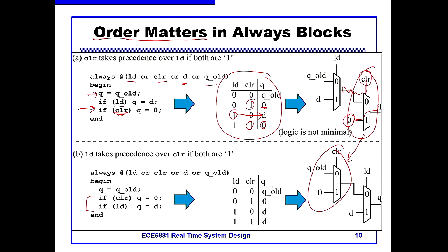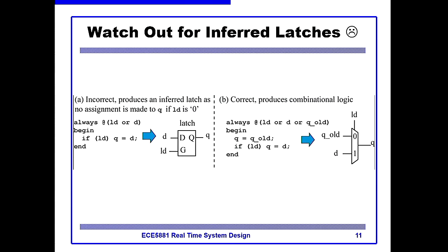Alright, so a little bit of confusion there. Within an always block, order matters. Outside, in assign statements, it doesn't matter. Alright, so this is a fairly nuanced problem that can happen, and it's called inferred latches. Alright, so I need to explain this. It's a little bit subtle.